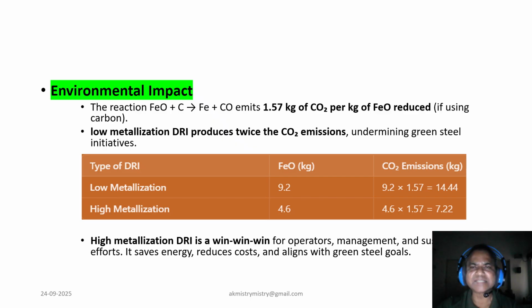We have already shown that with the presence of FeO, our fuel consumption is increasing, slag is increasing, operational cost is increasing, productivity comes down, refractory has a lot of wear and tear, and cost of production goes up. So all of this is not going to be good towards achieving betterment of the parameters towards the benchmark data.